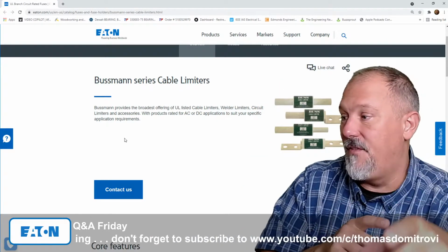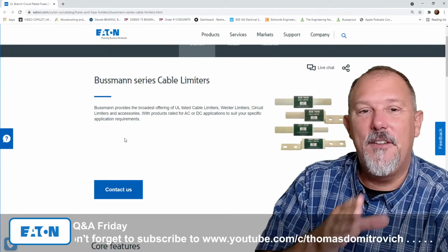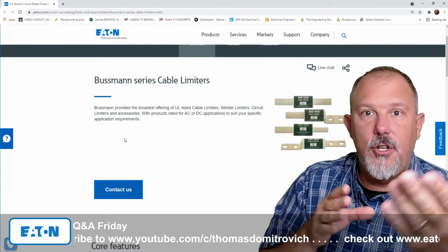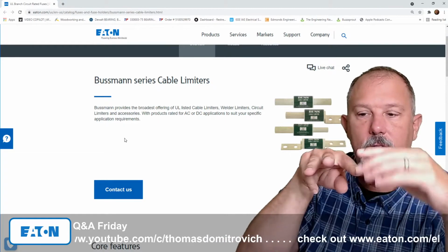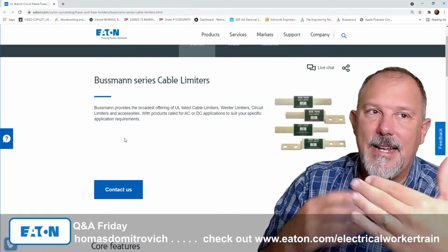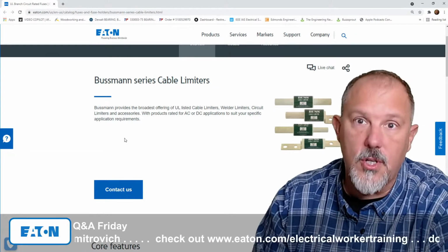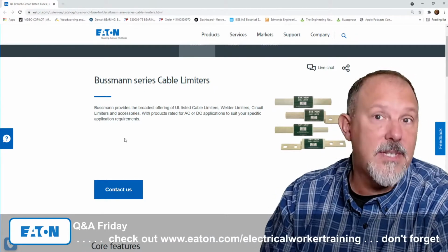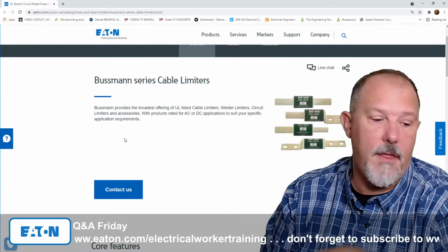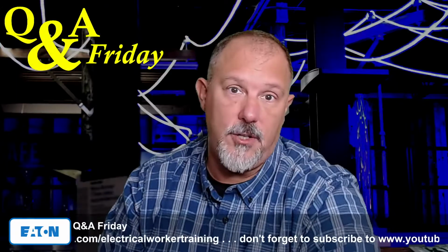So because of that, if I have 3 conductors and I only clear one, then the other 2 still are providing current. Can I really leverage that for a short circuit current rating? I would say no. In my opinion, because of what you pointed out, that would be an issue.